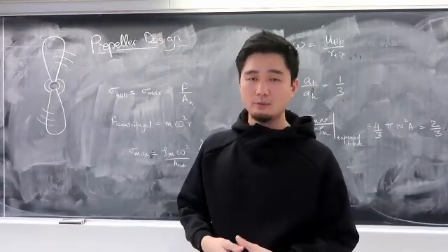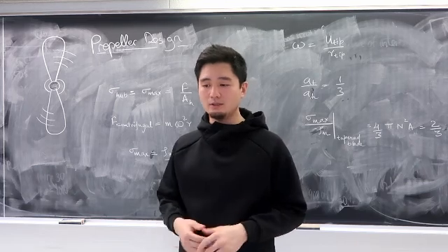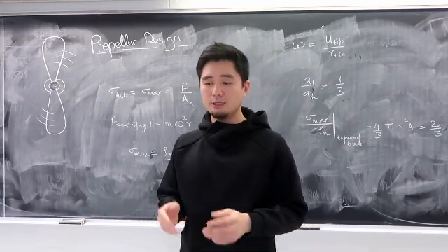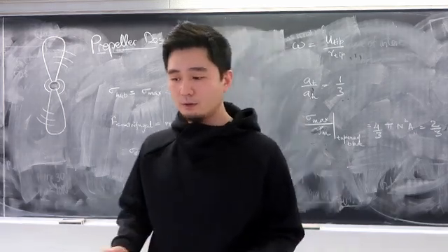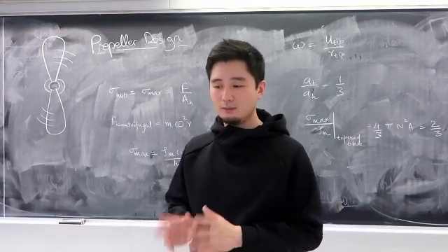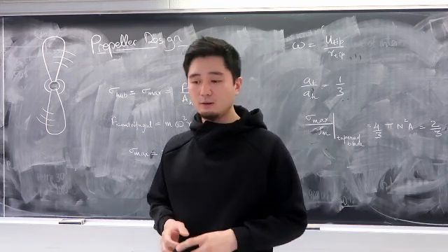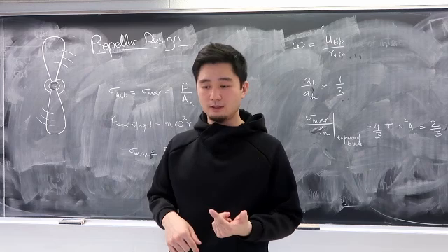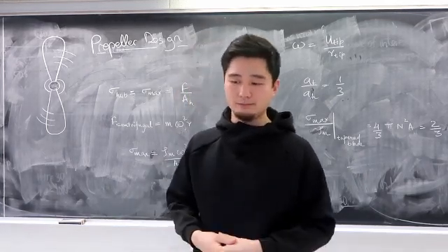For the effect of Reynolds number on propeller performance, in general, for Reynolds number below 500,000, a Reynolds number decrease would lead to an increase in drag coefficient and decrease in lift coefficient. So if lift coefficient decreases, then a direct effect is that the power coefficient and thrust coefficient would also decrease. A drag coefficient increase, then there's an increase in power coefficient, but a decrease in thrust coefficient. This behavior can be just explained by the boundary layer condition.